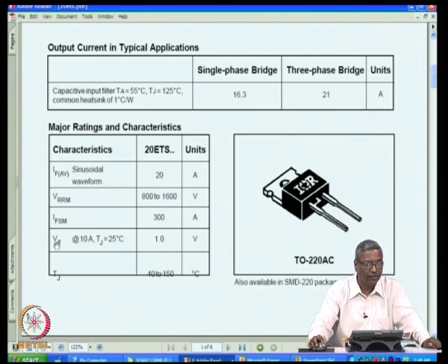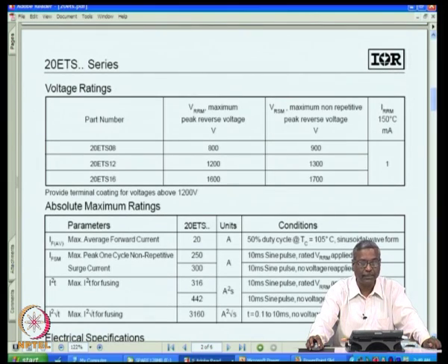And then you see the on state voltage. When the switch is conducting, the voltage when the current is 10 amperes is about 1 volt, and this is about the environmental condition that the switch is capable of operating anywhere from 40 degrees to 150 degrees. Okay. If you again see a little more on the